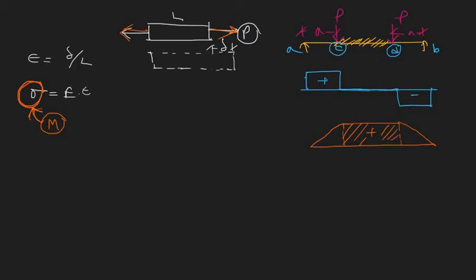and this case is known as, do you know? Yes, this is known as pure bending. We can say that this part from C to D is under the action of pure bending. Why? Because in this part there is no shear force. Shear force is 0. Got it? So due to this pure bending, we will calculate the stress on this beam element.